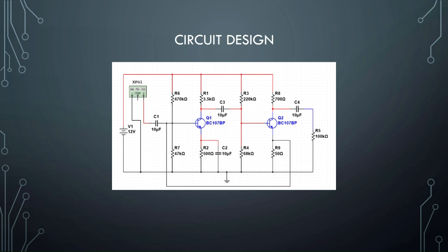For the feedback effect, the feedback current is combined with the input current at the base terminal, modifying the effective input signal seen by the amplifier. The feedback current helps control the overall gain of the amplifier. Increasing the feedback current reduces the gain, while decreasing the feedback current increases the gain. The feedback also compensates for non-linearity in the transistor and other circuit imperfections, improving the linearity of the amplifier.